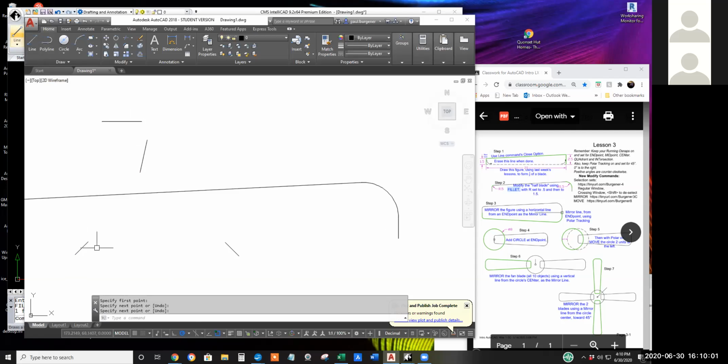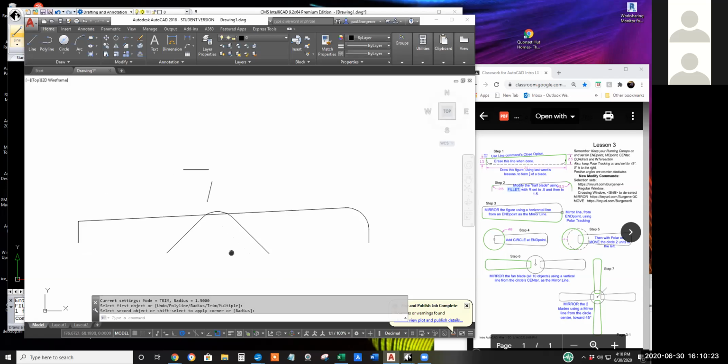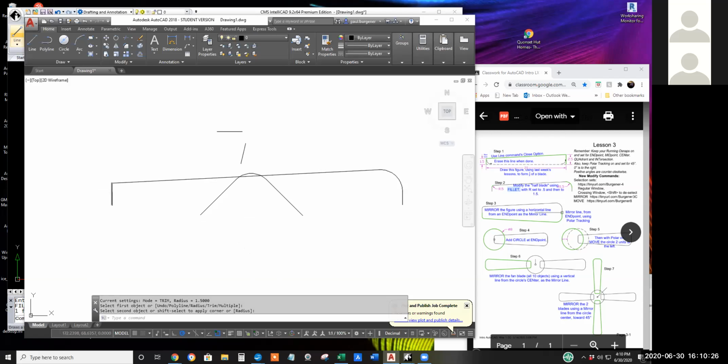I'll fillet these two lines at the 1.5 radius, and you'll see they lengthen so that the 1.5 radius arc can perfectly fit between the lines, like placing a pipe bend or an elbow in a piping system. Getting back to our page 1, I'll launch the fillet command again, right click, pick radius, set it to 0.5, back where I had it from practicing, and click near the two ends, and there's our radius.